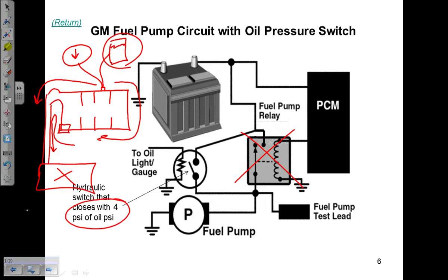We'll address this later, but let's say that your fuel pump check valve is leaking, which is a common issue. Let's say the pump itself, the check valve is leaking. So our bleed down is occurring here. If we pinch off this rubber fuel line right here, we can prevent the gauge from dropping. So now let's say it holds at 30 and is not dropping anymore. We can do our injection service now.